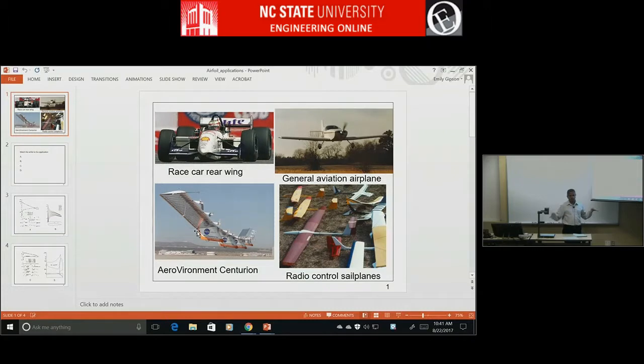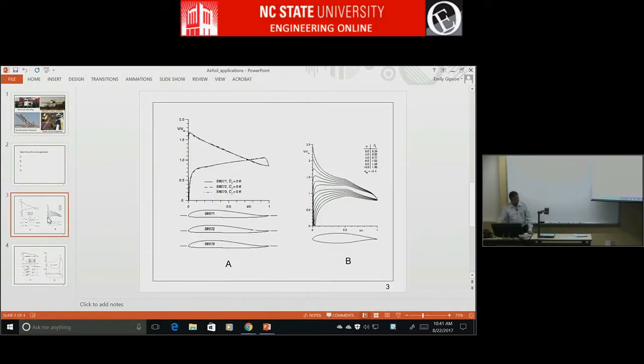The tail usually provides balance in most airplanes. That's not there. The airfoil has to provide that, and it has to provide stability. So you put the CG forward of the 25% chord, and you reflex the airfoil trailing edge so that it generates positive pitching moment. Right, so you can see the airfoil is tilted up here in the trailing edge.